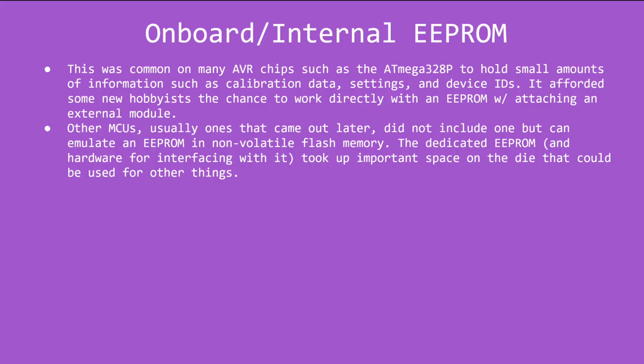There is a downside to that. If you finally used up your EEPROM's write cycles, that's a useless part to the MCU. I guess in some cases that is a use case for having a socketed ATmega328P on the Uno Rev 3. You could just replace it with something else because you've used up the EEPROM, I guess.